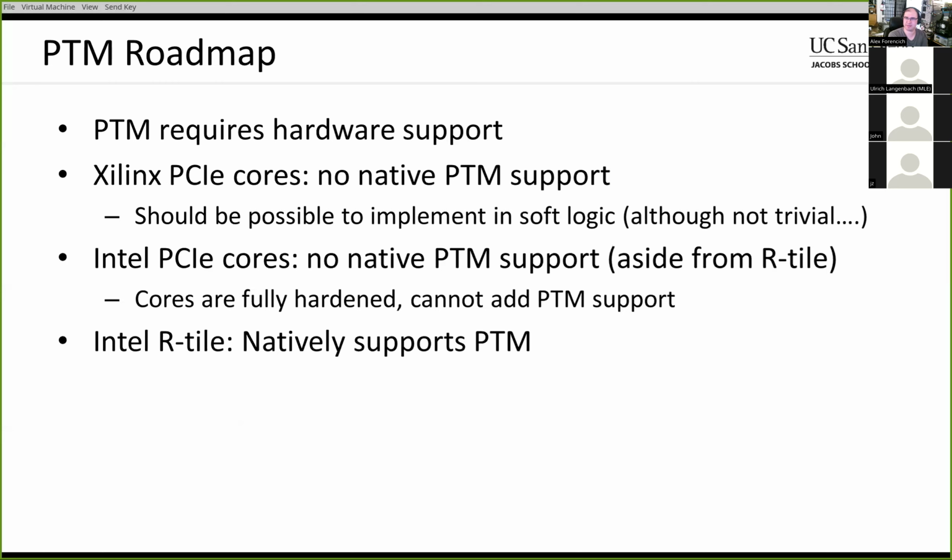But I think it's possible to implement it in soft logic, although it's going to take a fair amount of work because you have to be able to at least extract and timestamp these PTM messages and also send them. If you can't send them, then we might have a problem. But we've got to be able to timestamp them both coming and going. That's the main thing that needs to be implemented in order to get performance.